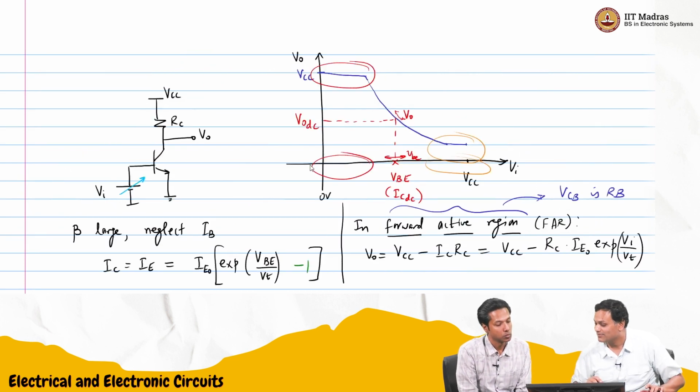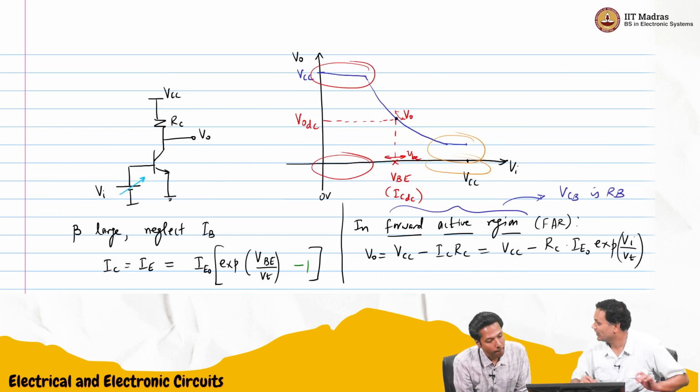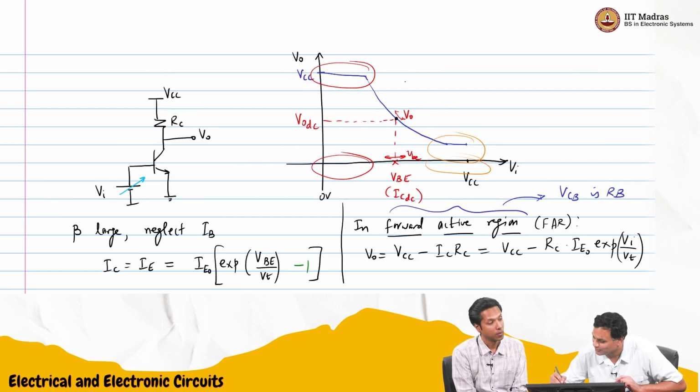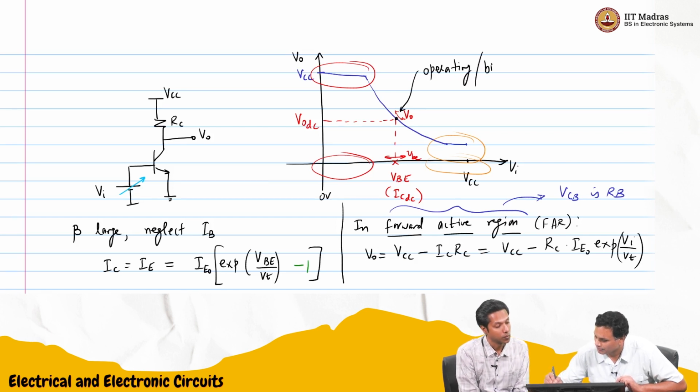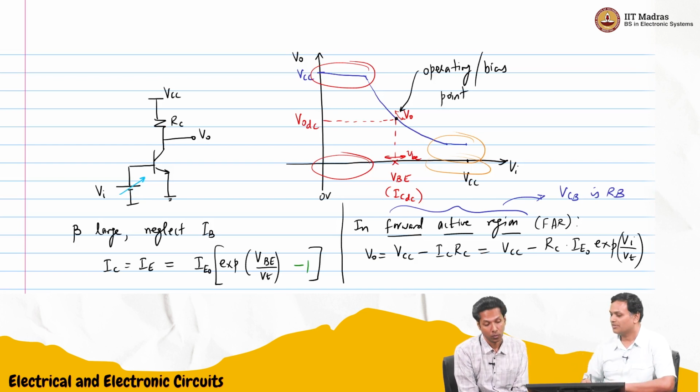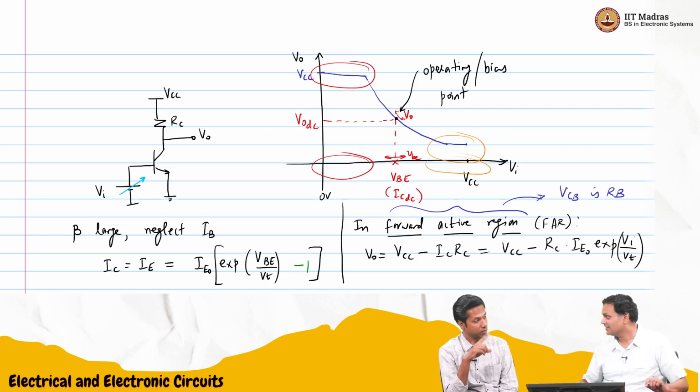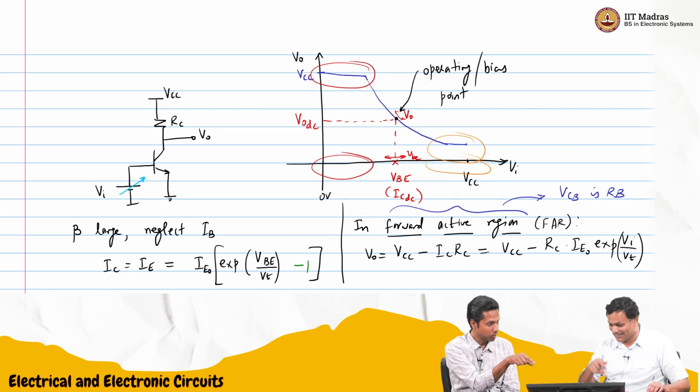And since we said small signal, this particular point is called the bias point or the operating point. Right. So this point is the operating point of the amplifier, or sometimes quiescent point. There are several names for this. So bias means that the previous circuit we discussed, we can use that to generate this. That is correct. Capital VB.